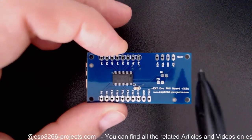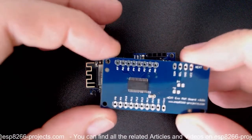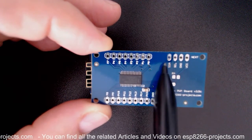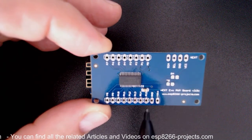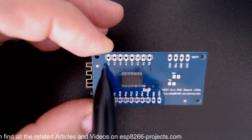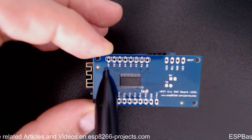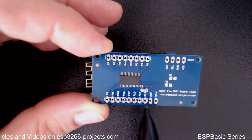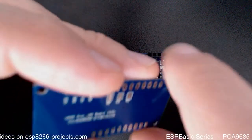On the top we have the IC itself. We have the decoupling cap. We have very nice connectors for all the pins that we are interested in. So basically on the left side we have the first 8 LED connections, from P0 to P7, and on the right side we have the other 8 from P8 to P15, and obviously a ground and a VCC.